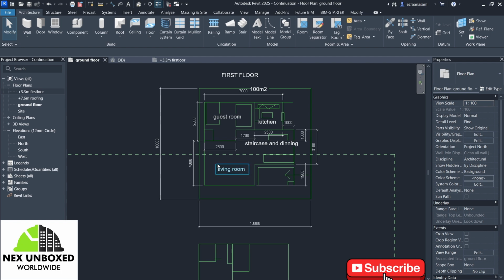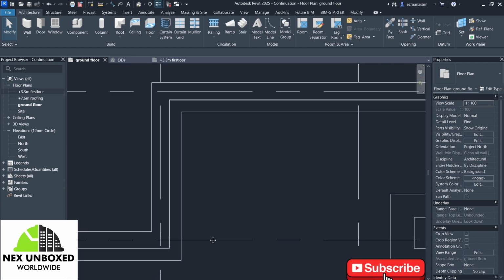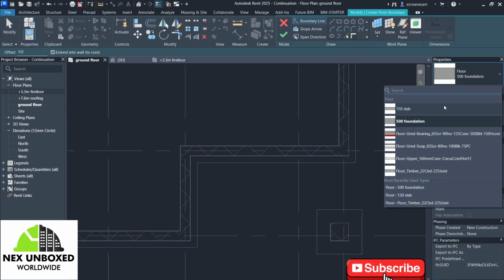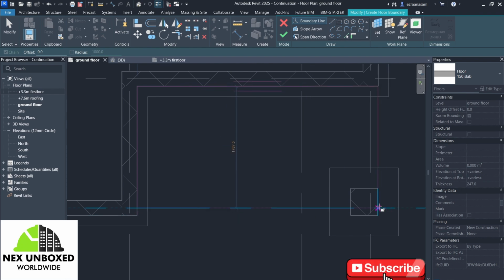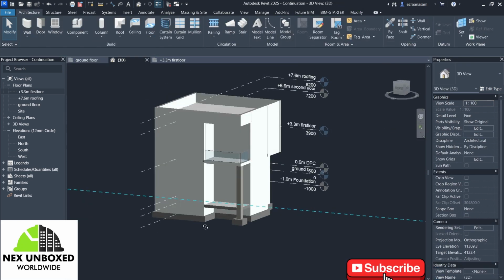Okay, so let's go back to the ground floor, and here we will design our floor. To design our floor, we'll come back here, not roofing, sorry, floor, architectural, and then we'll use the normal slab. And the normal slab, we will click on this one from the wall itself, like this, and it's going to be on the ground floor. And then we click on OK. So let's go back to 3D. You can see we have it.